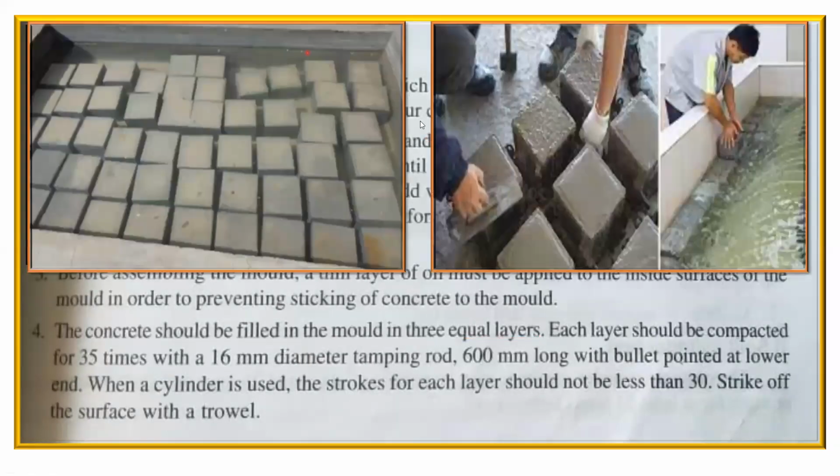And once that is done, you can see here, these people have cast the entire cube and struck off the excess concrete. So once this is done, next day you have to come. Let us say now you are doing the concreting of this. Next day you are going to come, take it out, and do the demolding of this. Take it out and immediately keep it in the curing tank for curing purpose.